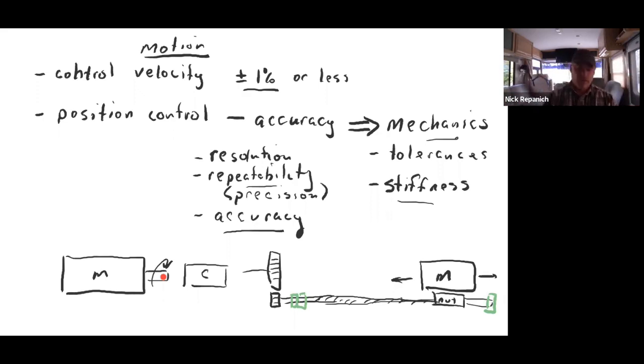The trouble that you get into with designing these things is this motor shaft is really short and it doesn't seem like it's going to deflect. But it does, it has a spring constant. So the trouble with doing motion control design, you're trying to do a couple things along the way here. One is you're definitely trying to minimize inertia.